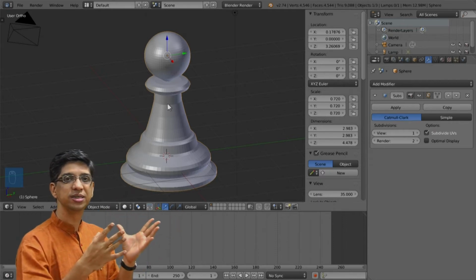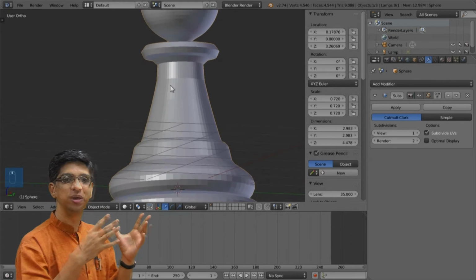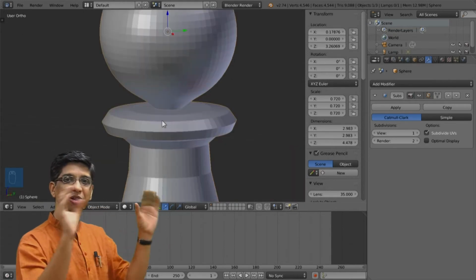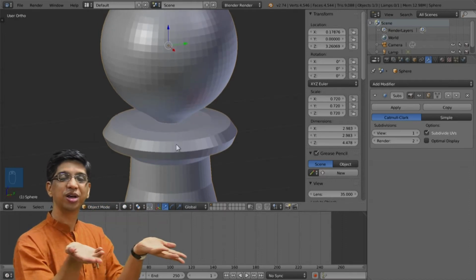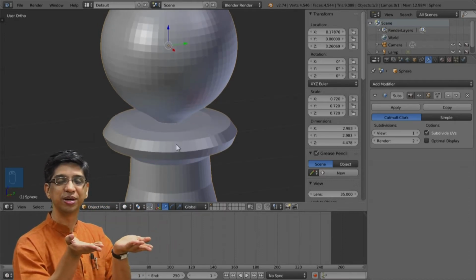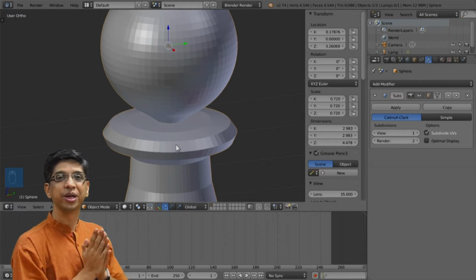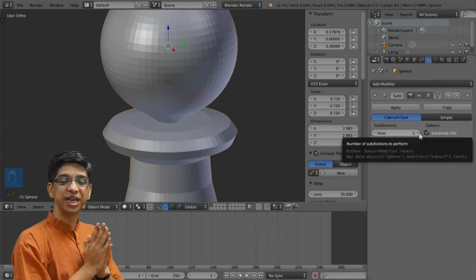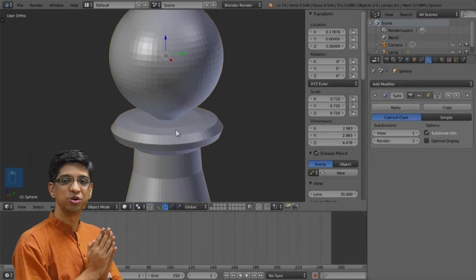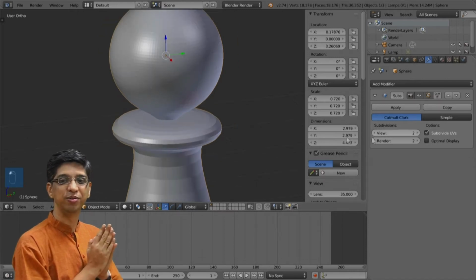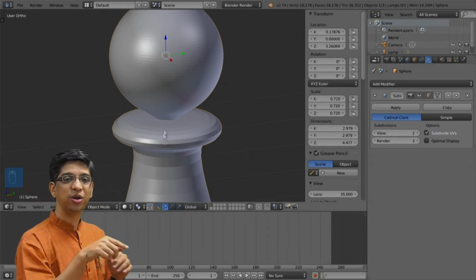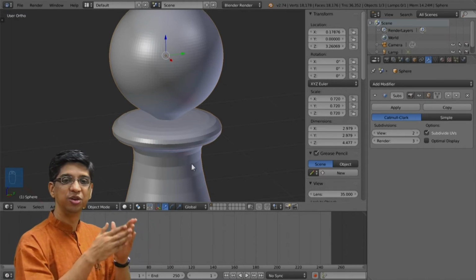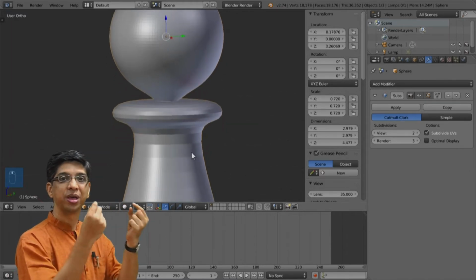Nitin will zoom in and show us that exactly below the globe, the rectangular disc has now been converted to an ovalish dish. So this is not what we wanted. Now we can change the view option to 2 so that it will be ideal to what we discussed, and also make the render option 3 so that it will render properly. You can also see that on the neck part you still have the faces.